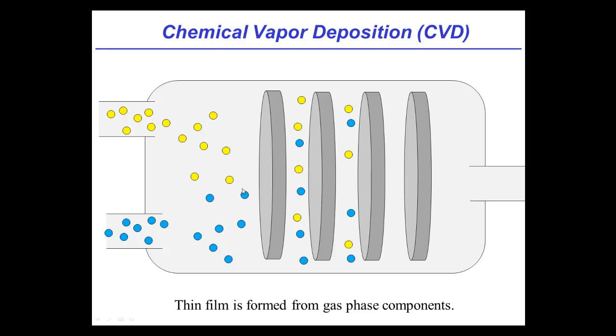And if I design the chamber right, it'll be pretty uniform across the entire depth. And what I should get is I'll deposit SiO2, and all the residue, which in the silane oxygen example is just a combination of moisture and hydrogen, will come out of the chamber. And so what this allows us to do is deposit as opposed to grow. So we can deposit films, the uniformity can be pretty good, and we can put 100 wafers into this chamber at a time and deposit them all. So this is called chemical vapor deposition, therefore, for obvious reasons.